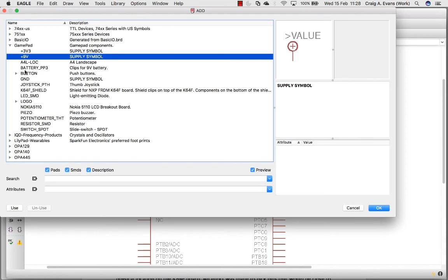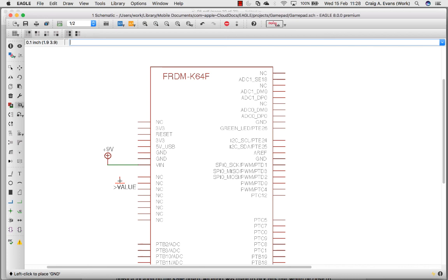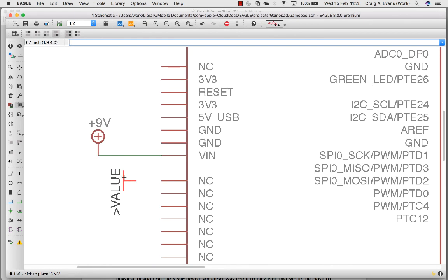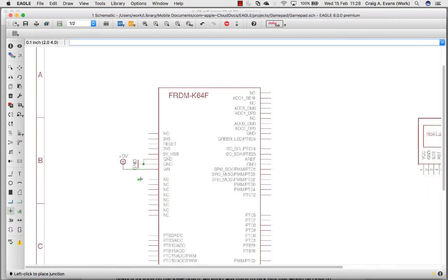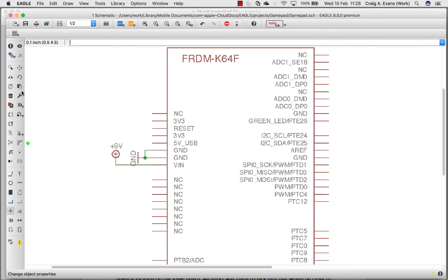So add in the ground. I'll just connect. Let's put a net there just to force it to be connected. There's another ground symbol over here. So copy this ground. If you overlap the pins like that and then move it just to check that it's connected, it saves drawing the line. So there's one more as well here. So we've got